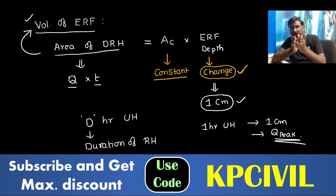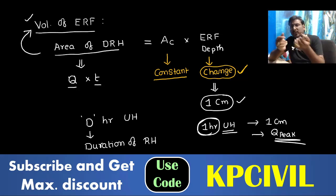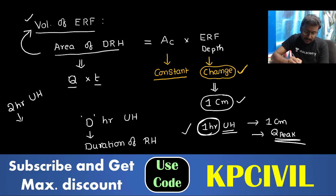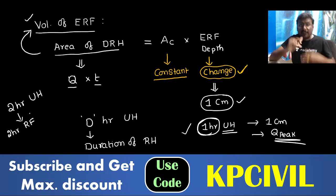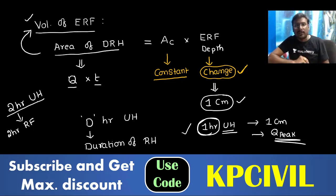Same 1 hour rainfall occurred in the same catchment for any time, you can apply this unit hydrograph. You understand? You can apply this 1 hour unit hydrograph and get discharge values. Again, you have plotted a 2 hour unit hydrograph. When 2 hour rainfall occurs in future, you use this 2 hour unit hydrograph.